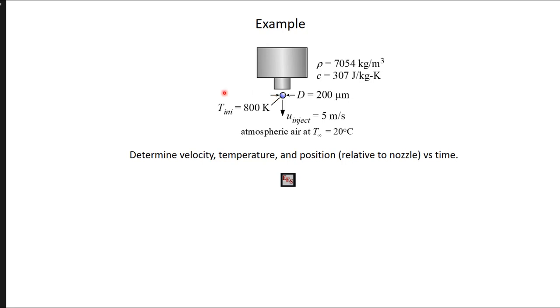So I guess by assigning this a single temperature, I've already sort of implicitly made the assumption that I can lump together all the material inside of this droplet and put it at one temperature. That implies that the Biot number is small, so I can use a lumped capacitance approach. I should check that at some point to make sure that's true, but it's a small droplet. We're going to assume it's very conductive, and so I'm going to assume that that's true. So we'll do this in EES.